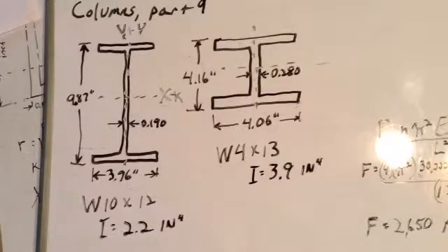Why did we choose a table of beams that all have the same slenderness ratio of 84.5? Remember that table in Part 8? Because that's the slenderness ratio of our 13-inch long buckled member of the failed tail boom of the Steel Stork. The slenderness ratio is KL over R. K is the end conditions factor of 0.65 for fixed columns. L was 13 inches, and the radius of gyration of the buckled member is 0.1 inch, a tenth of an inch. So the buckled member's slenderness ratio is 0.65 times 13 over 0.1, which is 84.5.